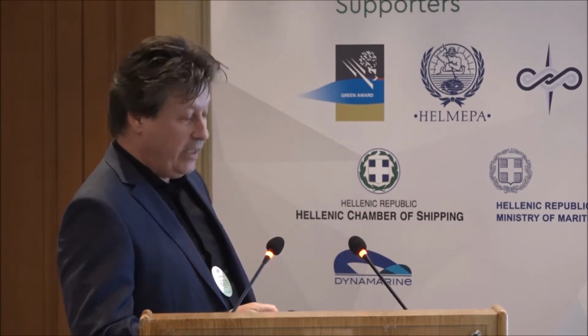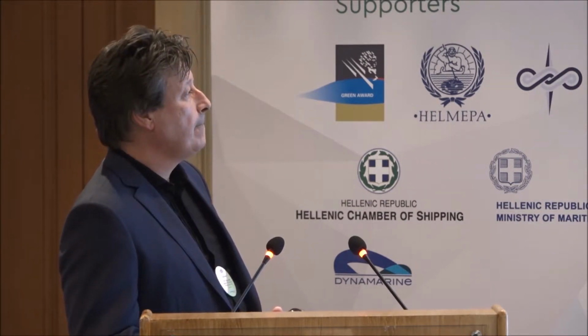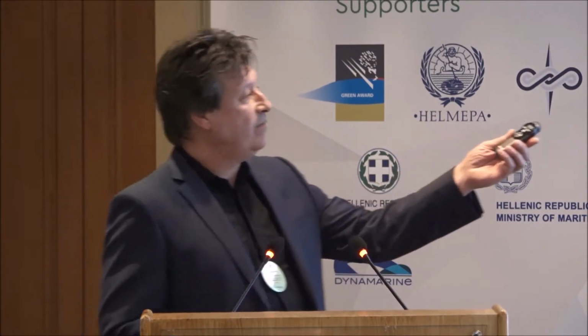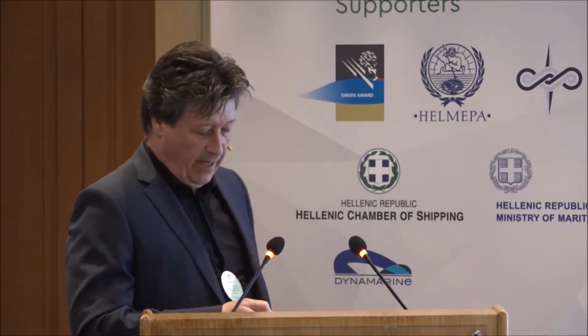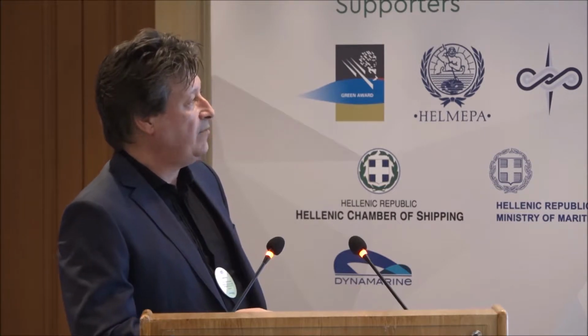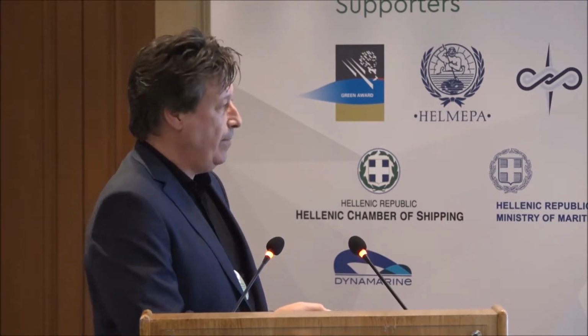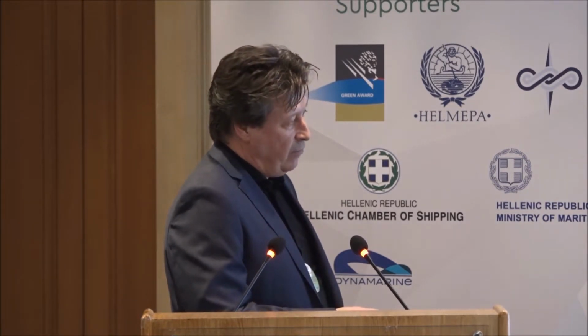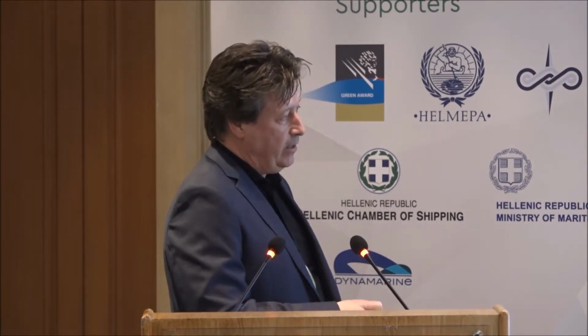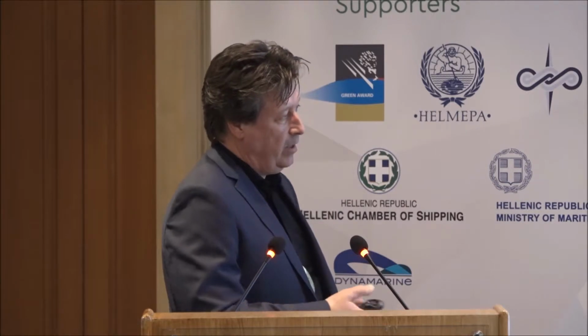So this previous curve, parallel side curve, that is showing the fenders in relation to the host vessel. So on one side you've got the shore fenders, on the other side you've got the ship-to-ship fenders, but then you also have to line up the ship-to-ship fenders with the guest ship parallel side. So therefore that now just shows the ship-to-ship fenders in relation to the guest ship parallel side.